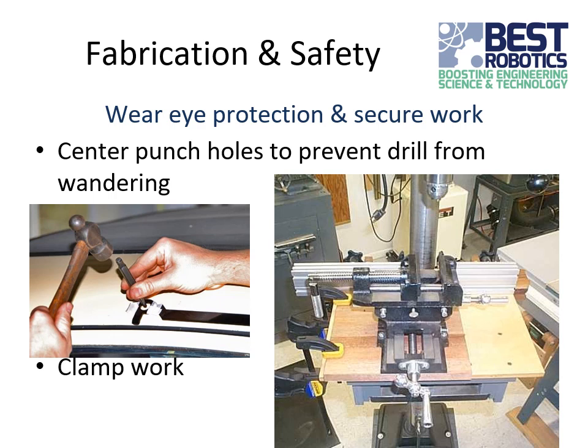And you want to make sure you give it one good clean whack. You don't want to sit there and hammer it with multiple hits, because it can bounce around and make multiple holes, which defeats the purpose, because then the drill can go from one hole to another, and the whole point is to keep the drill from moving.